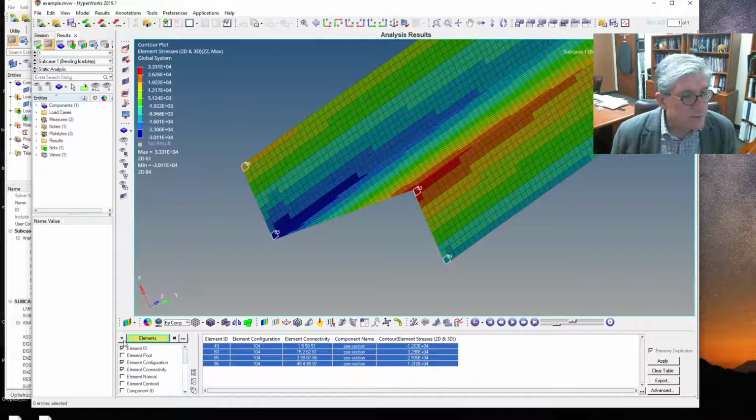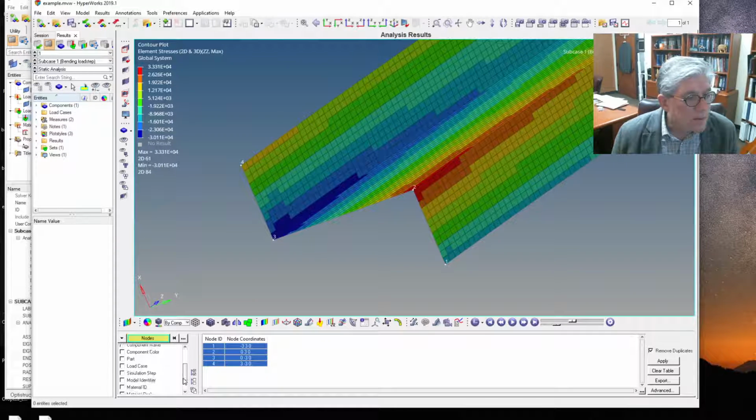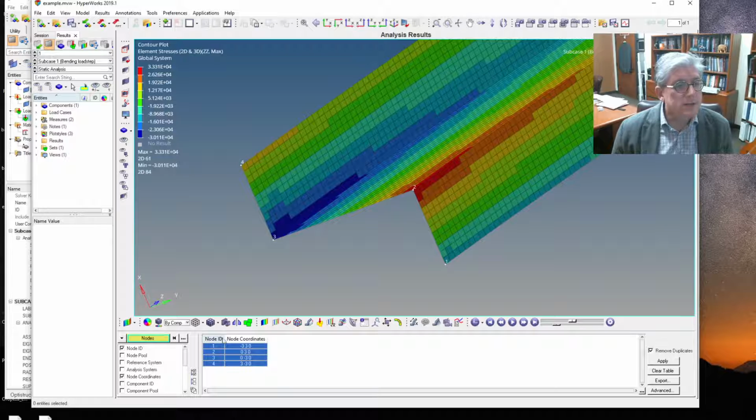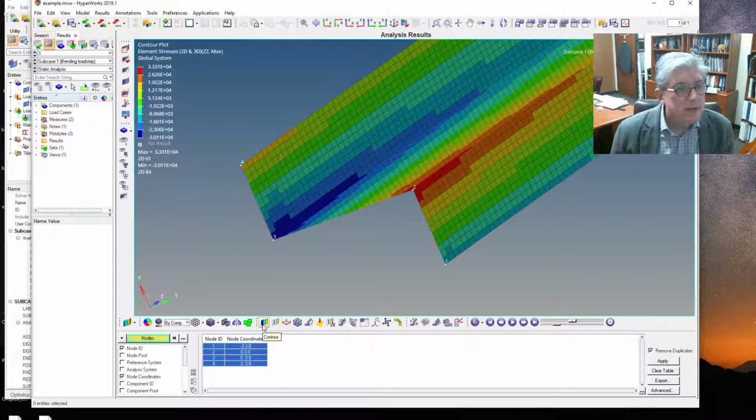If you want to, we can also plot out some displacements. So I'm going to pick the nodes. And then I'm going to pick that node, that node, that node, and that node, and that'll write out the coordinates of those nodes. I believe I can also tell it what to... Can I? Oh no! If I wanted it to display the displacement, I would have to go back and shade the displacement, and that would give me the displacement. Okay. But anyway, that's kind of good.